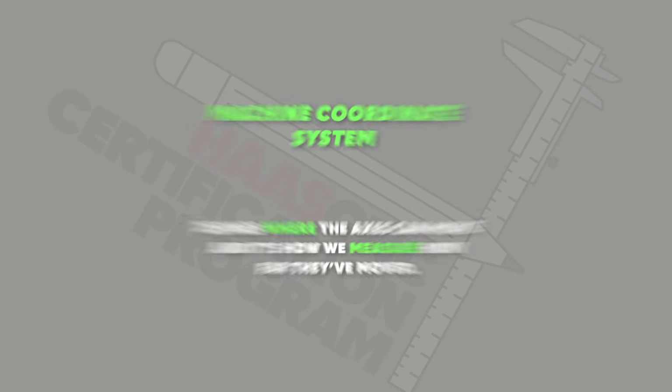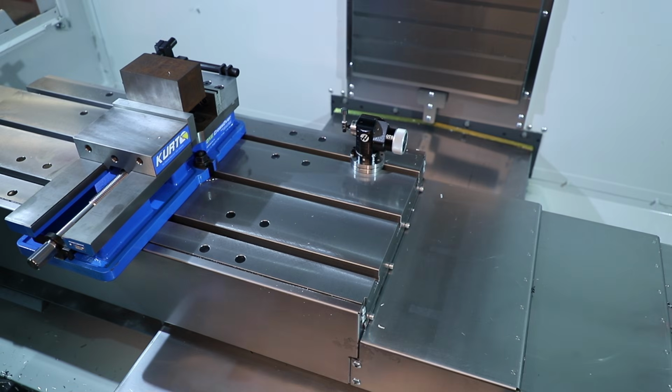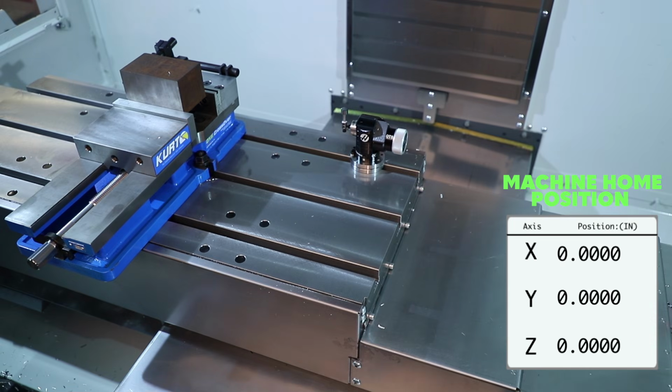The machine coordinate system defines where the axes can move, and it's how we measure how far they've moved. It basically tells the control where the table and the spindle head are in relation to each other. The machine coordinate system starts at 0 at what we call the machine's home position. On this VF3, the home position for X and Y is here in the front left corner.